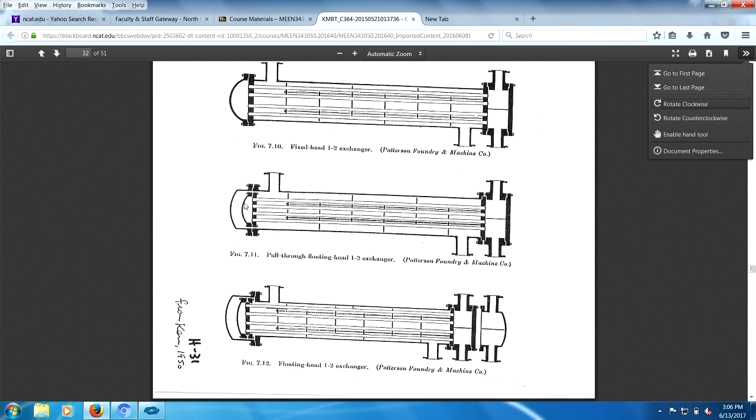And that means the tubes can expand freely. They got a lot of expansion in here. In fact, this is probably a bad design. There's so much stuff here. So the stuff comes in, the tube bundle is floating. This is called the tube bundle, right? We already said that. And so that takes care of the expansion on this.